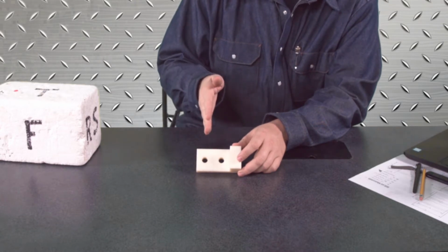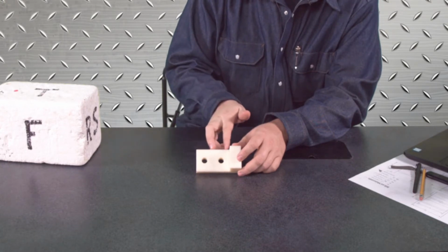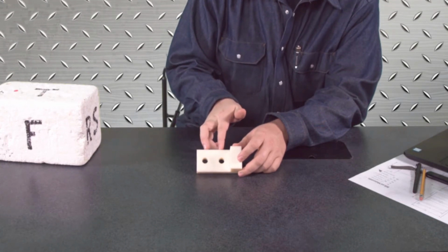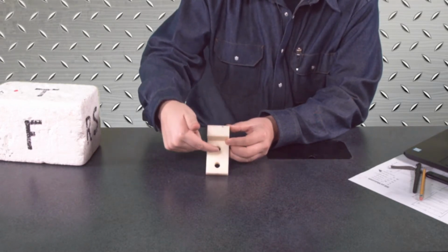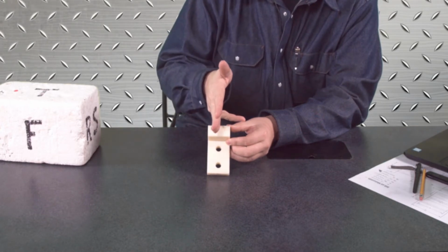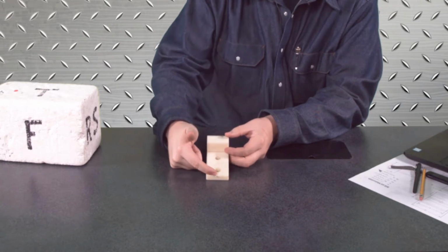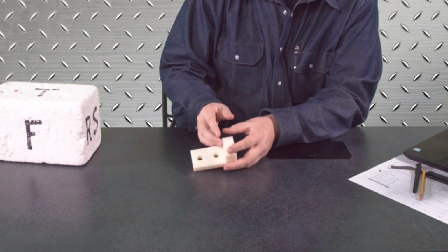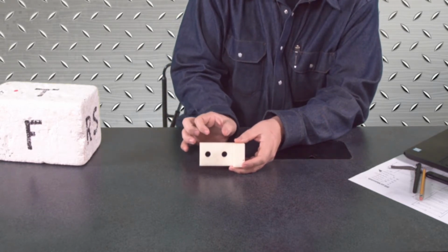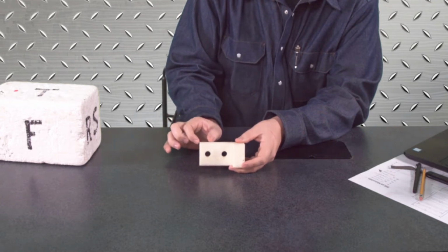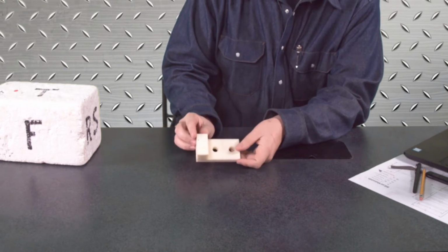Now, I can have center lines going through these holes as well, either this way or this way, and that'll let me know where the center line is on these holes, okay? And I can also have another center line going up the middle of this object to actually split the object in half and let you know where the center of this part is, or it could even let you know the center of these holes as well. And then off of those center lines, you can build dimension lines, and they'll actually tell you the distances between these holes and the distances from the end to the center of the hole as well. So that'd be the use of the dimension lines.